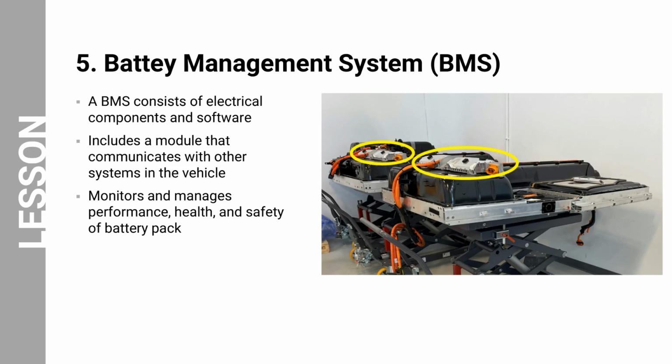Note that the location of the BMS may vary as the exact location depends on several factors, including the vehicle's design, the battery pack's cooling system, and the manufacturer's preferences. Most commonly, the BMS is built into the battery pack. Manufacturers may also integrate the BMS in a separate enclosure with its own cooling system, which can help to keep the battery cells at a consistent temperature. Manufacturers may also integrate it in multiple locations so that if one BMS fails, the other BMSs can still function and keep the battery pack safe. The primary functions of the BMS for an EV battery are safety, performance optimizations, health monitoring and diagnostics, and communication.